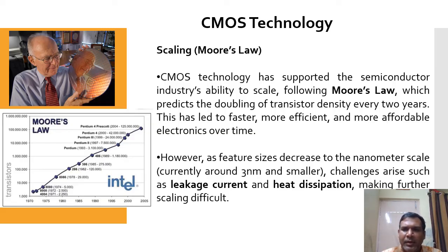like due to the scaling of the devices at the lower dimension, there will be a short channel effect, then time dependent dielectric breakdown, hot electron effect will appear, then velocity saturation will appear, okay. Then drain induced barrier lowering, this kind of phenomenon will appear. To avoid such kind of issues, most of the industries are